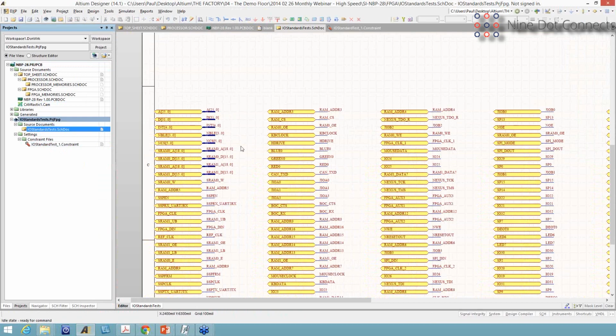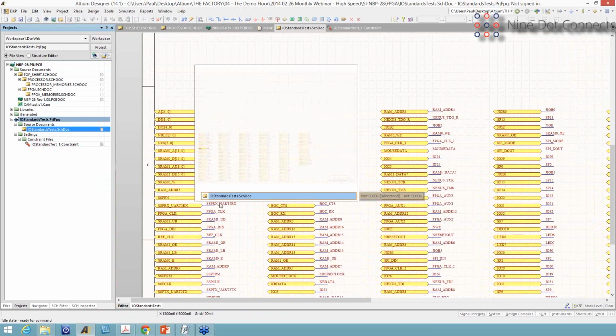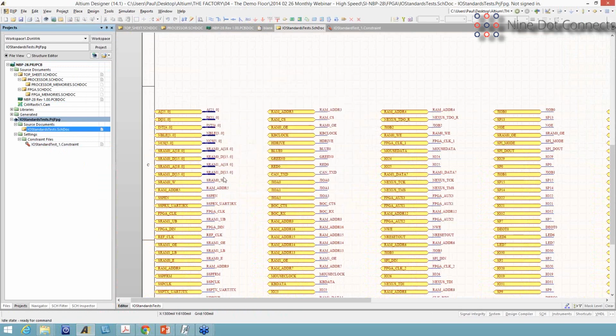And by the way, there's another really cool feature about this, and it's a little bit off on a tangent, but if you're doing a really large FPGA, there's a great wizard in Altium called the FPGA to PCB Wizard. If you set this up, and all this can be set up very quickly through SmartPaste, you can set up the ports, you can set up the names, and you can run that wizard, and Altium will basically create that sheet for you. So if you've got a really, really large design, this is a very fast way to do it. So something to keep in mind.